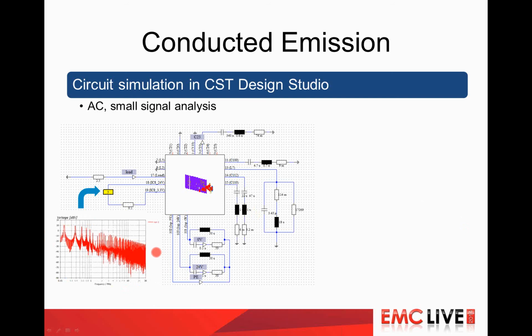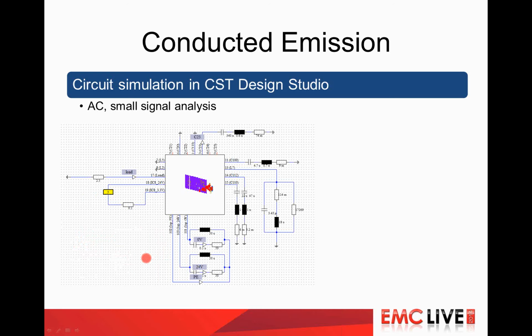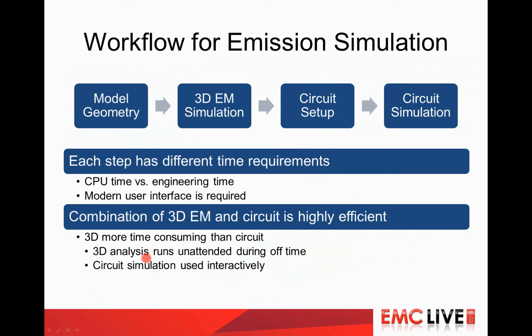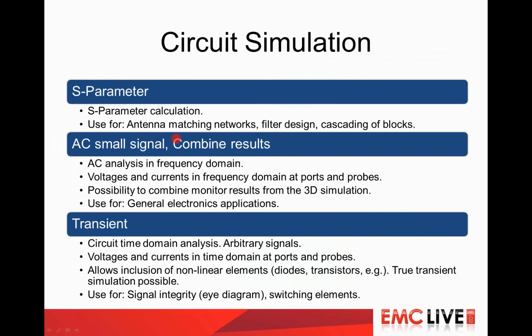Okay. Another question. Can the driving waveform be brought in from, it says LTspice? Yeah, sure. I mean, you can import basically the waveforms that you would like to use for the simulation. Again, if we come here to the different tasks that are possible in the circuit simulation, you can import a spectrum for usage with the AC task, or you can import a transient waveform and use this as an excitation to obtain then the results. So that's both possible.